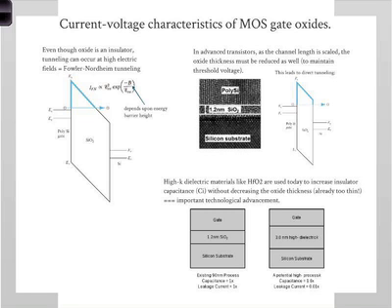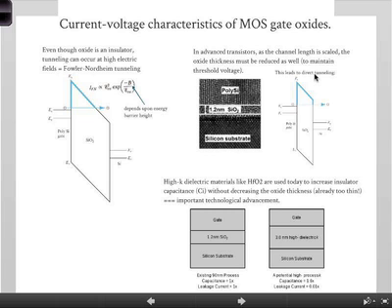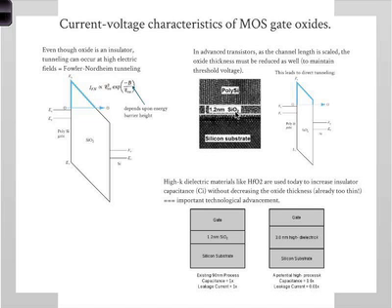Okay? To avoid this today, which you should be aware of, people use what are called high-K dielectrics. So essentially they try to increase the permittivity of the dielectric material. So instead of just using oxide, they use a fancier material called hafnium oxide, which has an epsilon which is larger than silicon oxide, which means that you can maintain the same capacitance, which turns out to be important. Okay, remember, capacitance goes with epsilon over D, by making D a little bit larger.